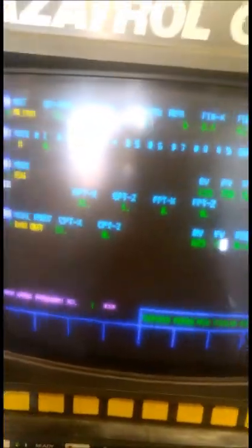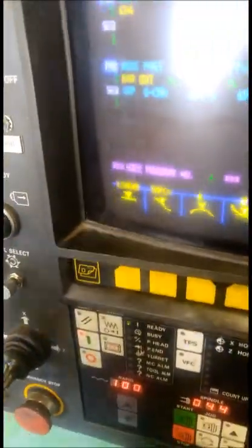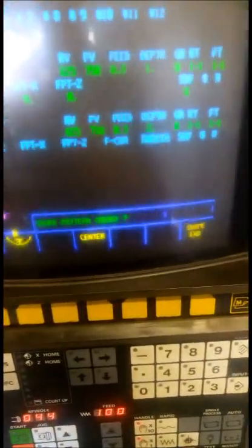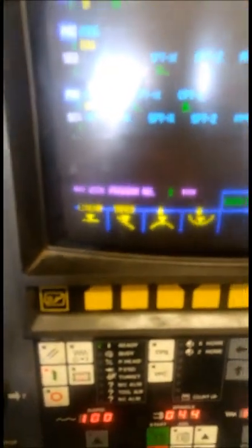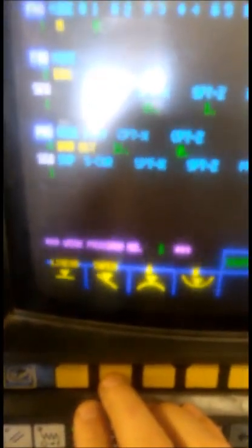Speeds and feeds, again, just hit auto. Set my roughing tool and finishing tool. Now you don't actually have to put a roughing and finishing tool if you don't want to run a finish op on this. Say I wanted to do a few different bar out operations or whatever, and then do a finish afterwards, I could do those all separate and then just do a finish one without putting a finish tool in all of those ones, I just want to rough. But in this case it's a pretty basic part, so I'm just doing that. So shape. This is where you start off by telling it what you want. With this part I'm going to be starting with a taper.